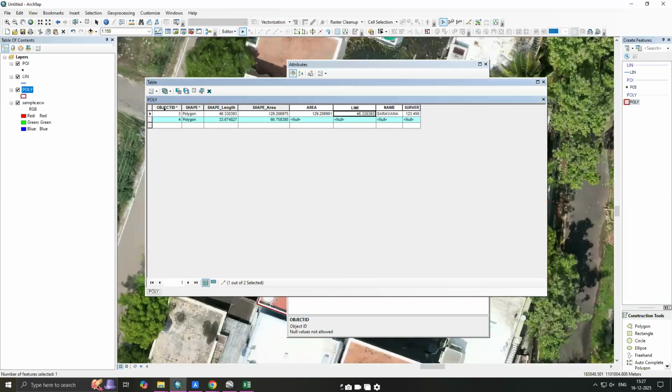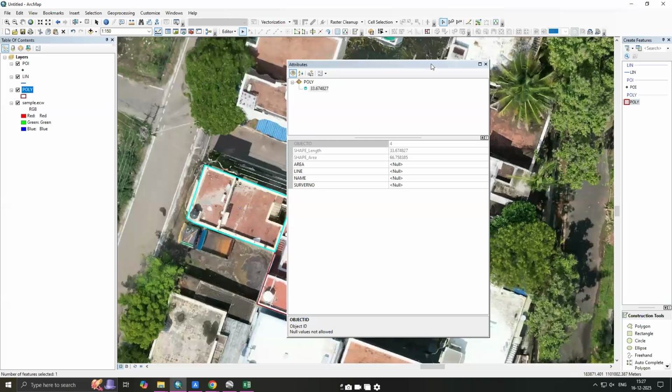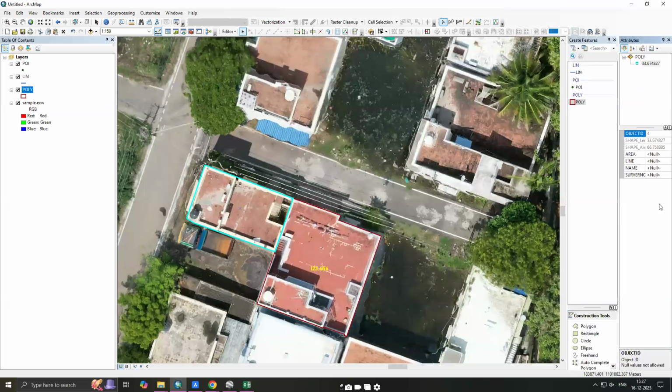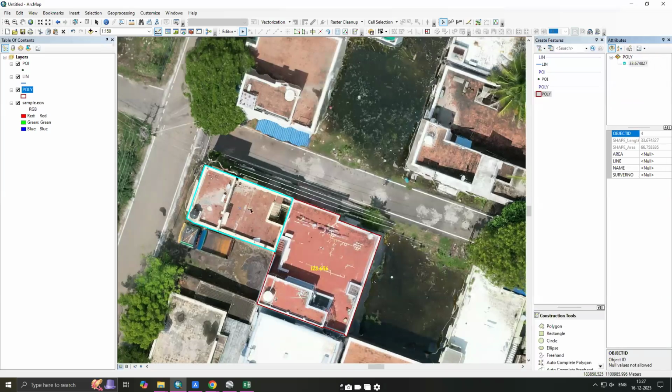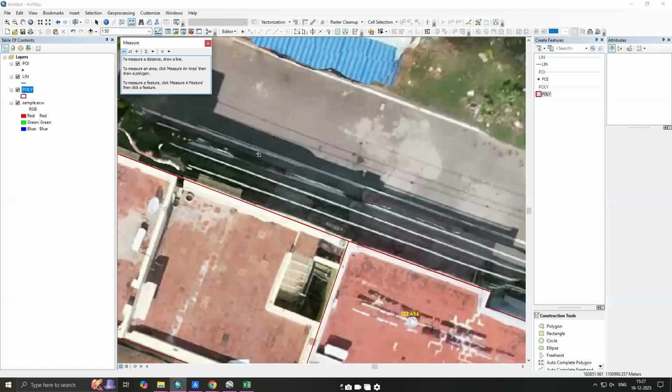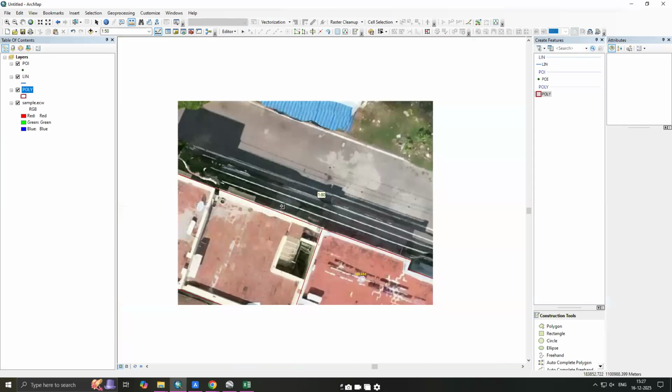So this process of extracting measurements from any image is said to be photogrammetry. Now we have extracted the survey data from photogrammetry, and it only has the size of the data. It will not have all geometric measurements, like what the angle is, or if this road is there, what is the distance of this road. We have to extract that. See, there is a scale here. This is the road edge. This is the building edge. You will see the entire length. What is the length of it? How much is it? Everything. So photogrammetry is taking measurements out of an image. That is basically what it is defined as.